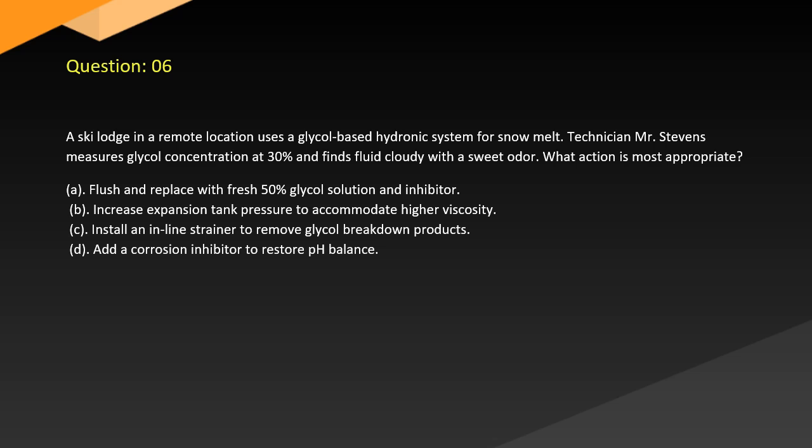Question 6. A ski lodge in a remote location uses a glycol-based hydronic system for snow melt. Technician Mr. Stevens measures glycol concentration at 30% and finds the fluid cloudy with a sweet odor. What action is most appropriate?